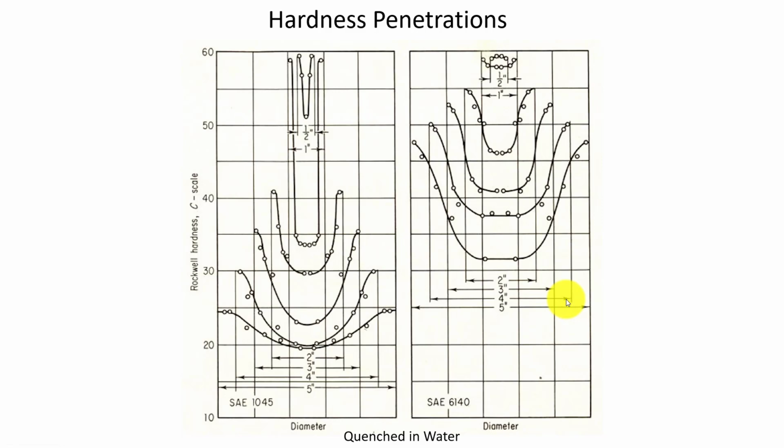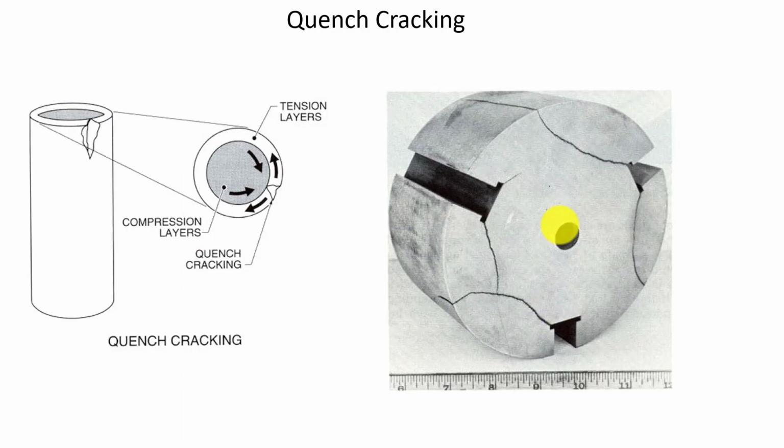When you're looking at the heat treaters guides, you might look for sections of effects of thermal mass or quench rates on part sizes. When we start talking about quench rates, and we talked about the fact that the different quenchants are safe, the metal could be a safe quenching, we could dump it in water and it's going to be fine. It won't quench crack. Some metals will quench crack in water. What's happening is when we quench that, the outer layer of that material is going to be in what? Tensile. And the tensile forces on it, because the inside is in compressive, is going to exceed the material properties, and we can actually develop a very small hairline crack.